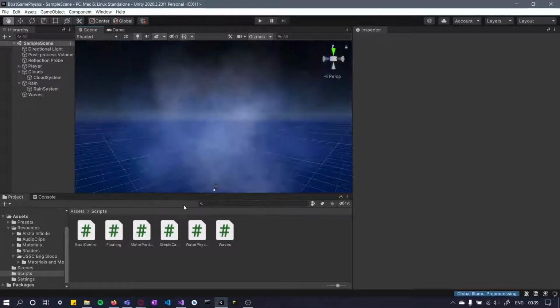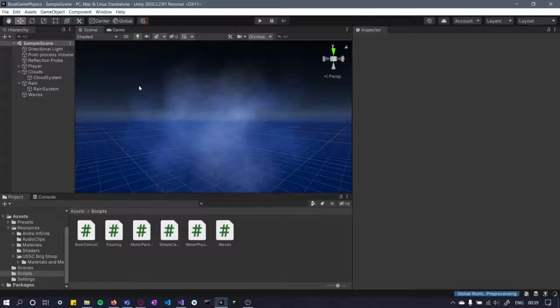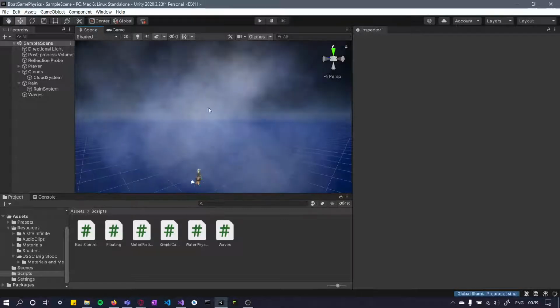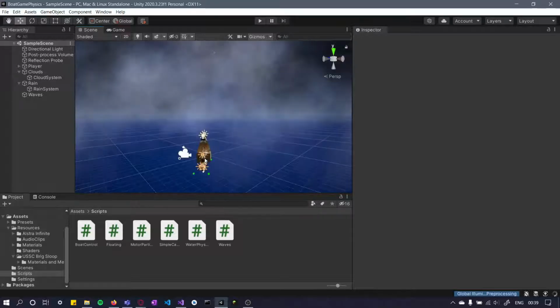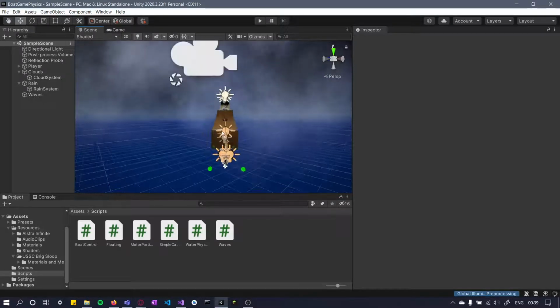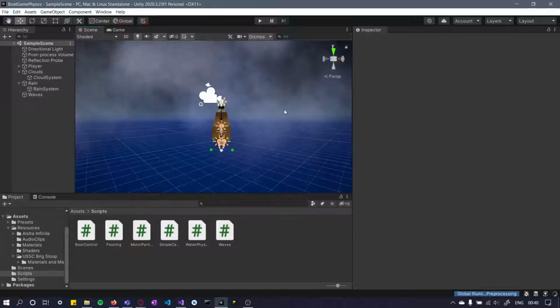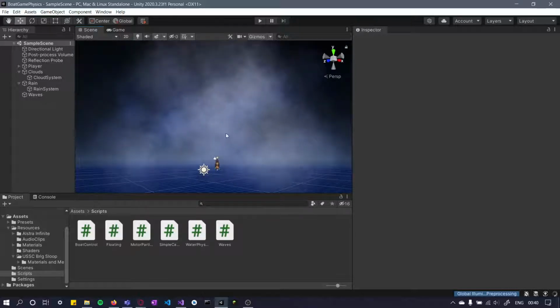And when made very dense, like let's say I want actual cloud cover on top, I can simply make this bounding box smaller and make this a lot more dense, because right now the transparency of the texture is high. So if I reduce the transparency, then it will become like clouds. Now this is what is called a volumetric particle effect, because it's not moving around. It is based on a bounding box, and it remains stationary. So that's what a volumetric particle system is known as. So it's less moving and it's more for the atmospheric look.